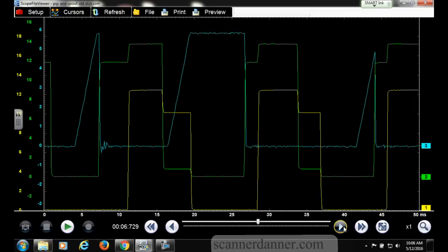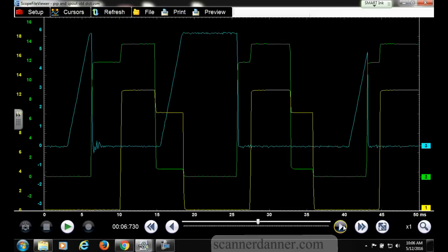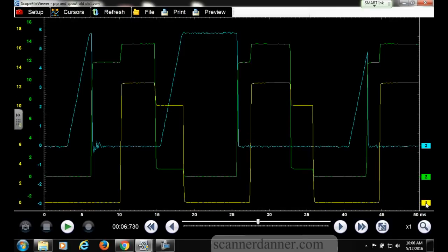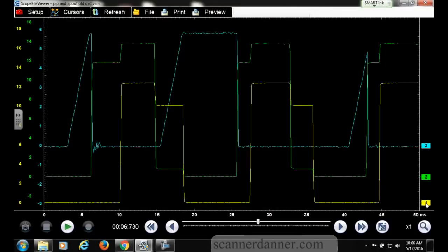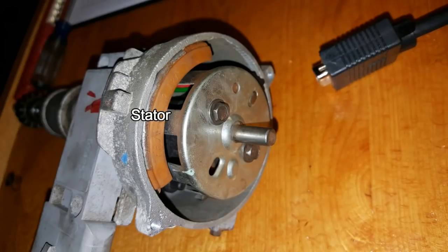Maybe there's like a chipped tooth on that thing. It's not a chipped tooth. Definitely not a chipped tooth. There's nothing visually on here. The old material would tell you to push on the stator, which is the top of the inside of the pickup signal, and if it was real soft, that was an indication of failure. I never saw an internal one that was soft, so I don't know what they were talking about with that. Nothing visually that you would see here, Randy, at all.